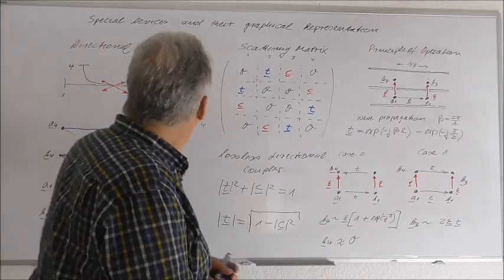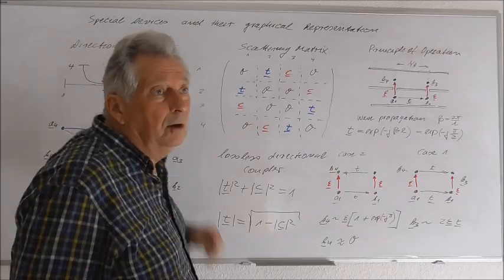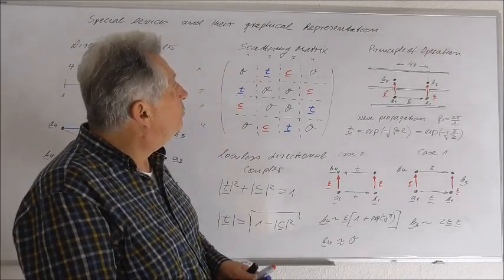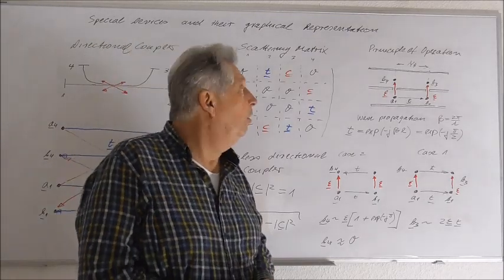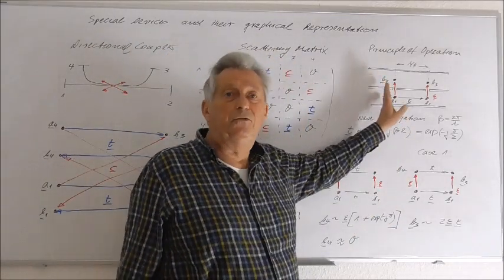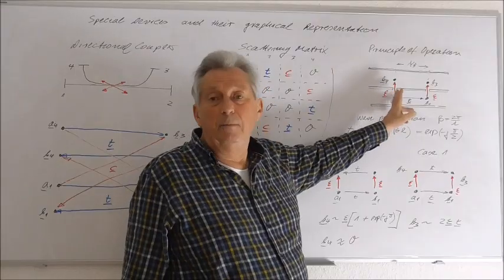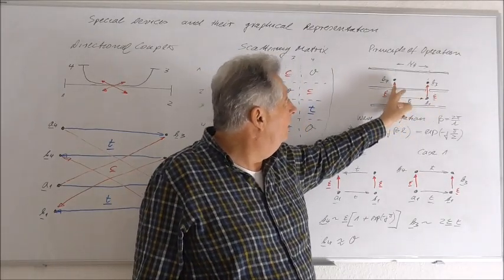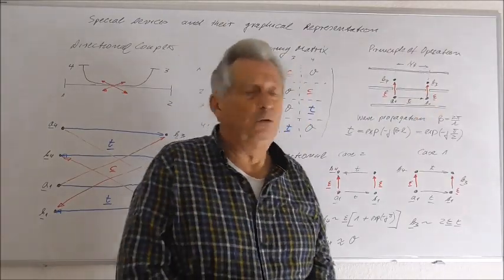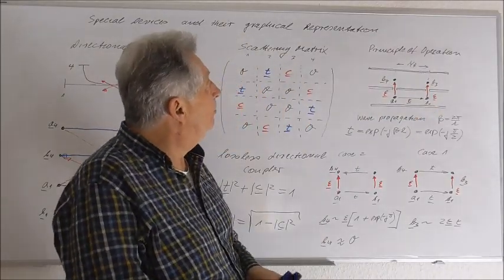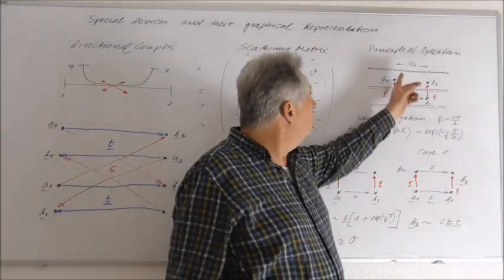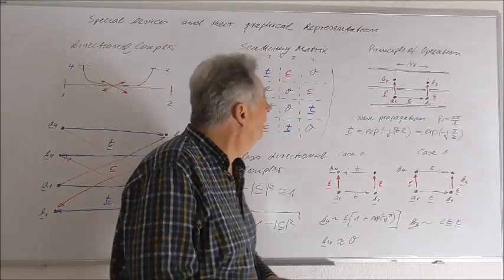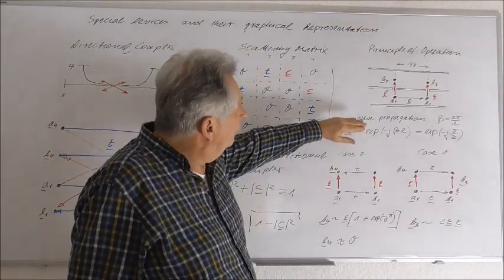So essentially, if I have a directional coupler built up of waveguides, these waveguides are essentially soldered on each other, and the simplest form of a directional coupler can be constructed with two holes. So a coupling will result through the two holes, and the essential point now is that these two holes are a quarter wavelength apart from each other. So we have here the wave propagation.